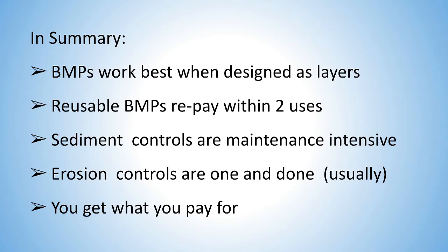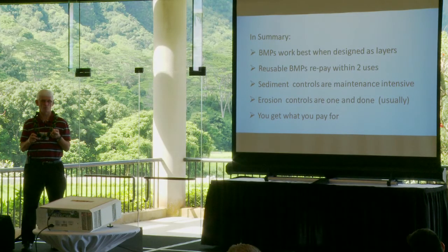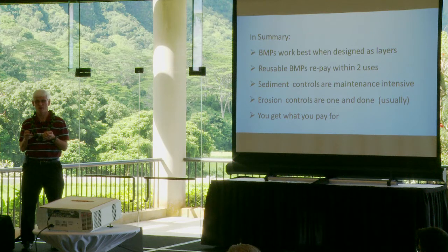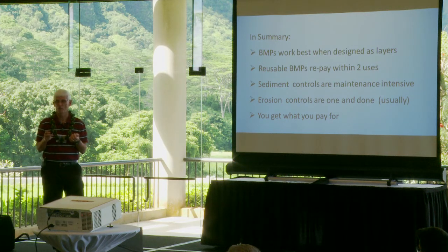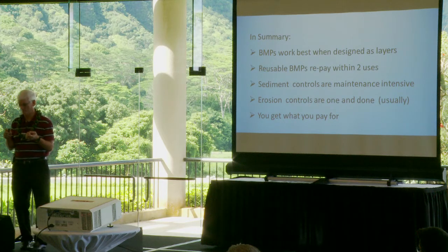So again, look for what's most cost effective for your project. If you're working a short-term project, you're only going to be there 3 months, you can go cheap. You're going to be there 2 years, 3 years, you're building a theme park that might take 4 or 5 years and cost billions of dollars, you don't want to be reinstalling a silt fence every 6 months. It's a waste of time, waste of money.